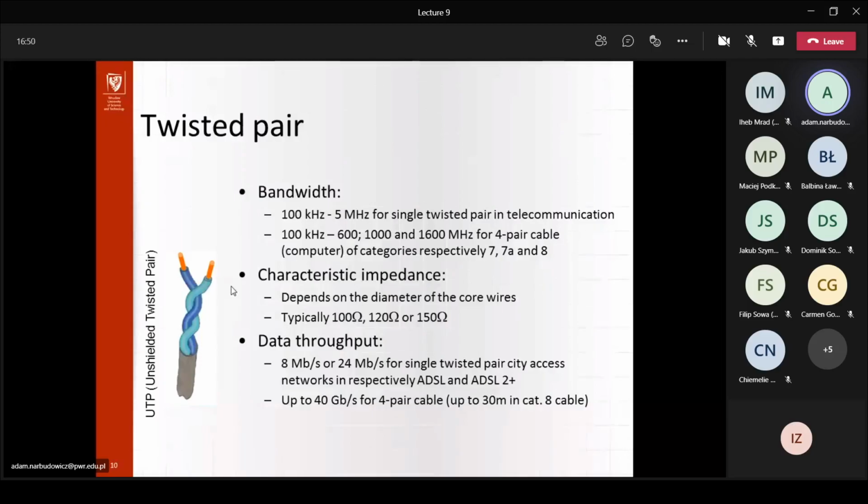So basically they would generate and accept quite a lot of interference, simply because there's no shielding. Of course, sometimes you will see shielding added, however, not in this case. And basically making them wrap around each other is one way of trying to combat the electromagnetic issues that we may experience here.